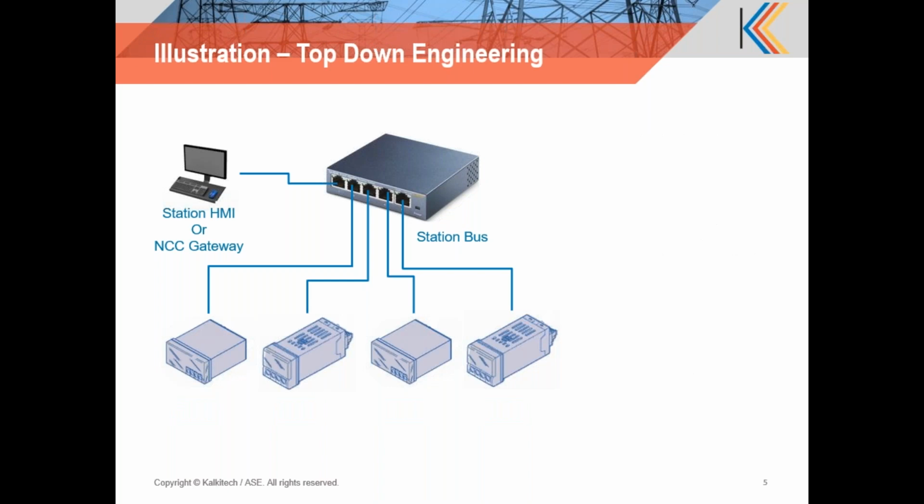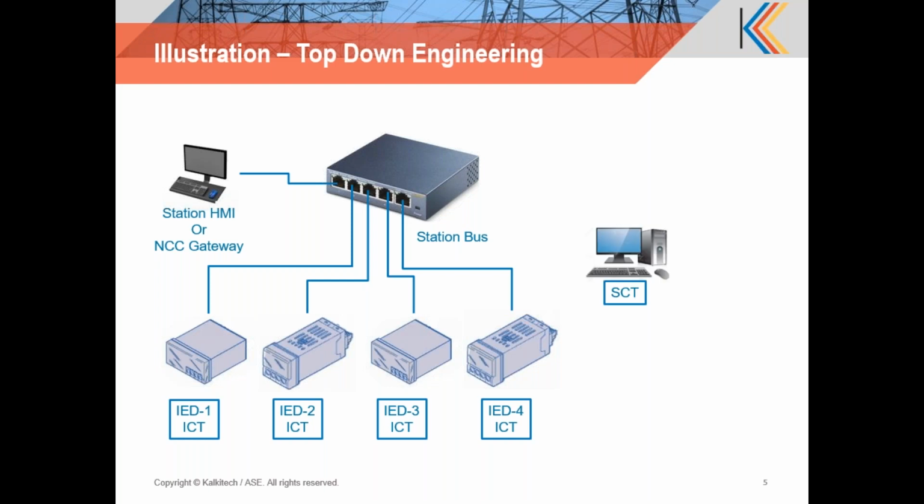Now, when it comes to top-down engineering, the IED configuration tools come into play here. These are tools that are provided by the IED vendors, and they incorporate proprietary technology. The other tools involved in this process are the centralized system configuration tool, that is the SCT, as well as a system specification tool, that is the SST. Now, the top-down approach starts with the generation of a specification by the SST role or the SST tool.